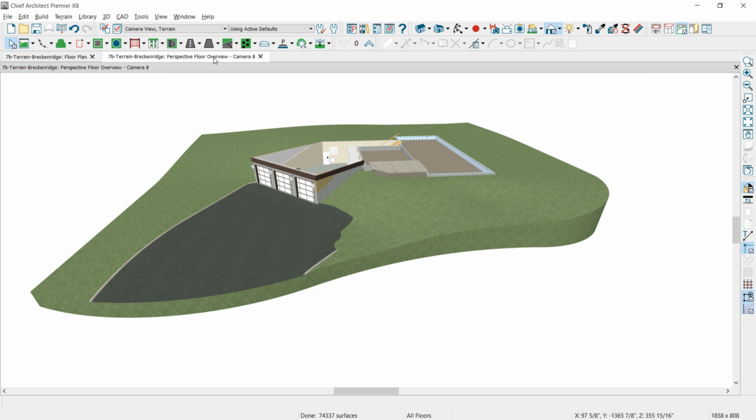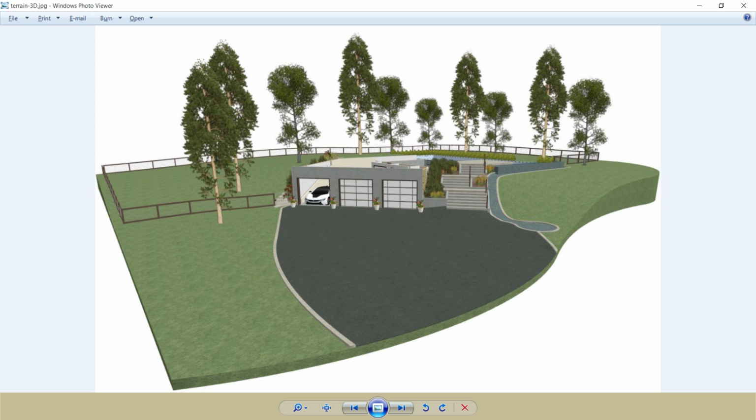In the 3D view, once I have the curbing placed, this cutout in this area will be where the pond comes in, and then I'm going to go ahead in the next couple of steps and show you how to create the stairs that will come down from this area. And with the stair tool, I'm going to start from the top of the slab from the porch and work my way down until it hits the road. That way I can basically be flexible on the number of stairs that are required, in particular on the last segment.